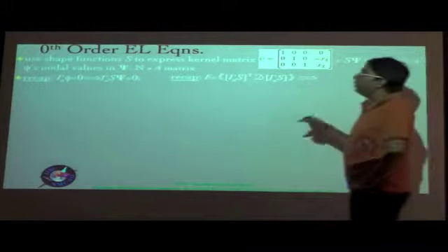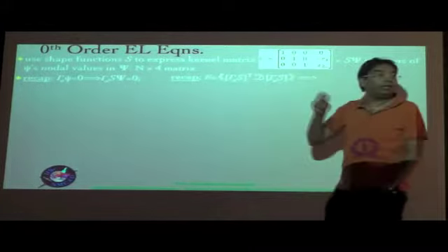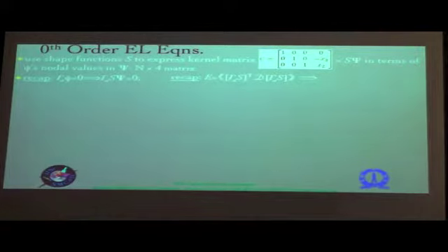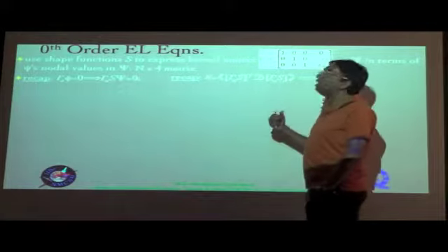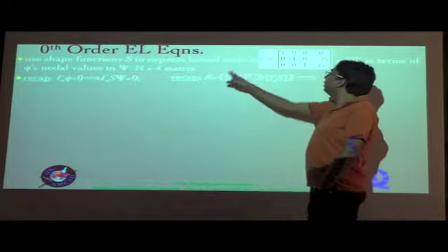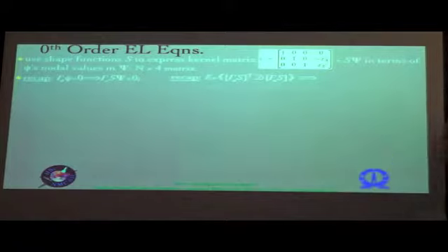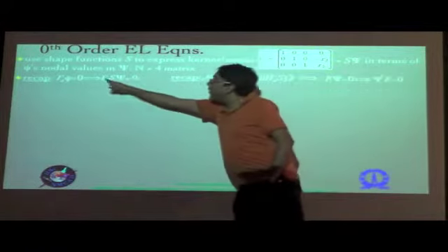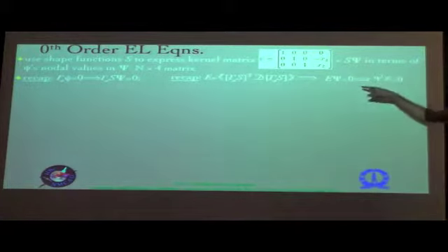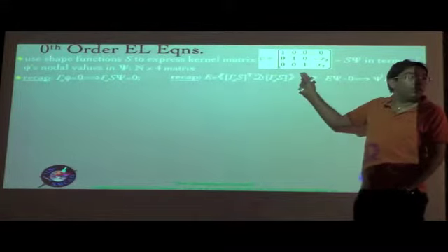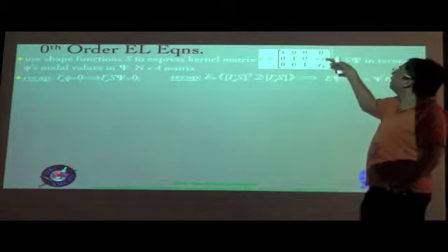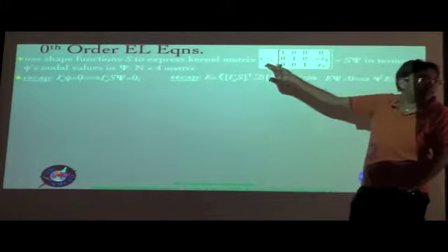Now from the previous slide, also recollect the symbol E that we introduced for this intermediate kind of stiffness matrix that we have. So basically it is this quantity, right? Now if you multiply this E with this xi, it is quite obvious that it is equal to 0, because xi is not a function of the cross-sectional coordinates, because it already has the numerical values of x2 and x3 of all of those quantities.